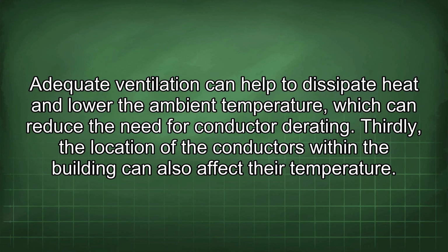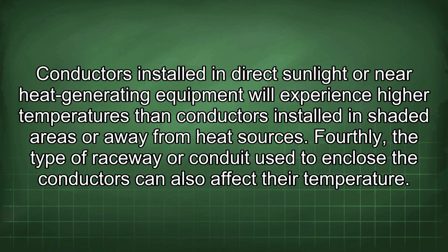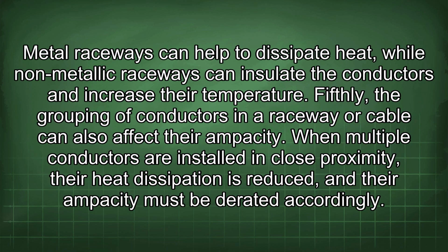Thirdly, the location of the conductors within the building can also affect their temperature. Conductors installed in direct sunlight or near heat-generating equipment will experience higher temperatures than conductors installed in shaded areas or away from heat sources. Fourthly, the type of raceway or conduit used to enclose the conductors can also affect their temperature. Metal raceways can help to dissipate heat, while non-metallic raceways can insulate the conductors and increase their temperature.